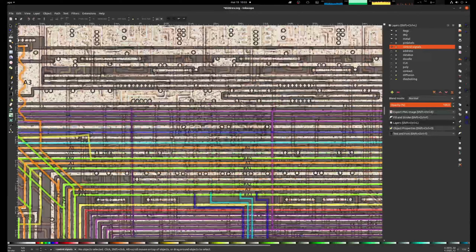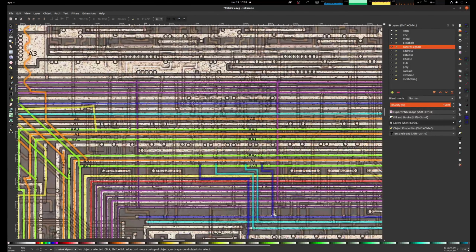And then I also found it also hooks off the second from the top, which is bit number 6 on the E register, which is this input output serial port pin. It goes into here, and it has something to do with this control signal, so I'm confident that we are in the right place.